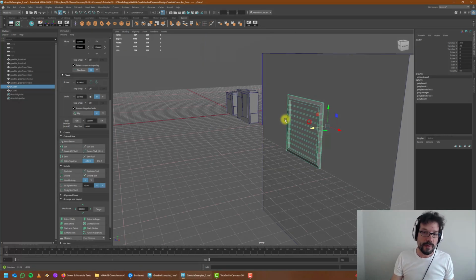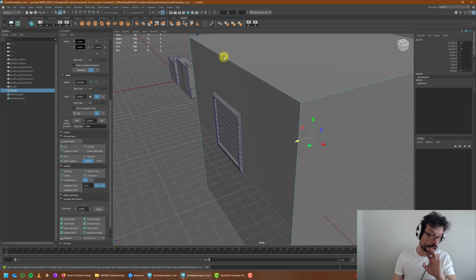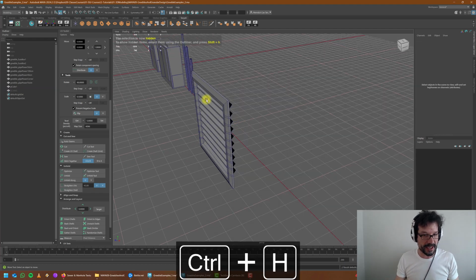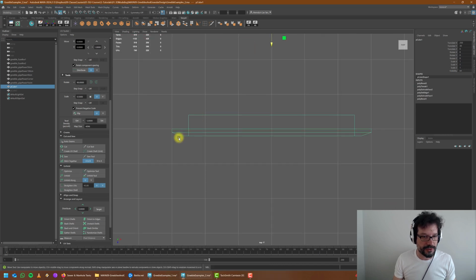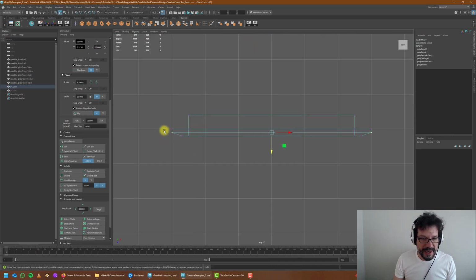Okay, so one way of fixing this issue is, if you don't want to create a greebly that requires a hole on the wall or hole on the place that it is going to be placed on, you can hide this by exaggerating some of the details. Instead of this object protruding just by 2 centimeters, you can make it protrude even more. So maybe let's grab these areas right here and push them backwards, or maybe let's keep them intact and push these instead.